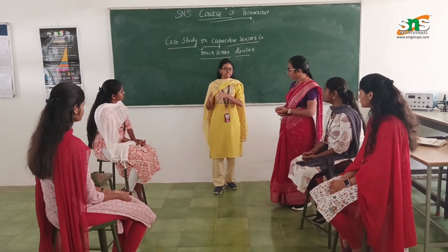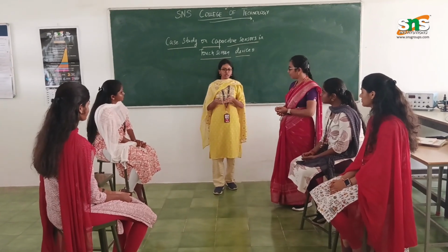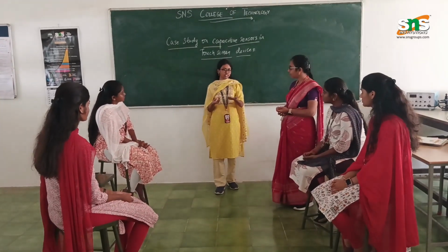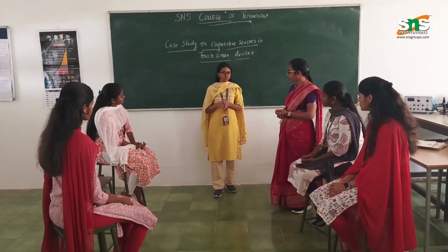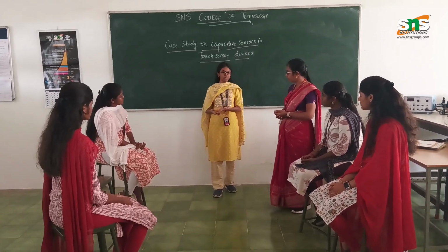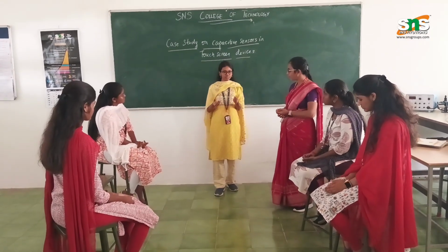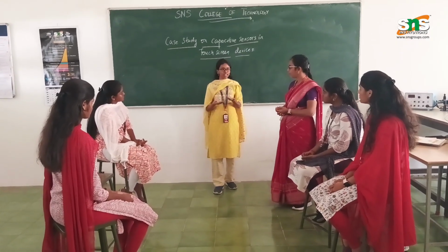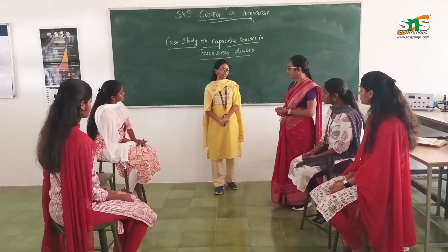It mainly depends on the electric field between two conductive plates, where when the human finger approaches the surface of the sensor, the electric field distribution changes. With the change in the electric field distribution, the capacitance also changes, so that the device considers this as an input touch. I would like to continue this case study with Yamuna.